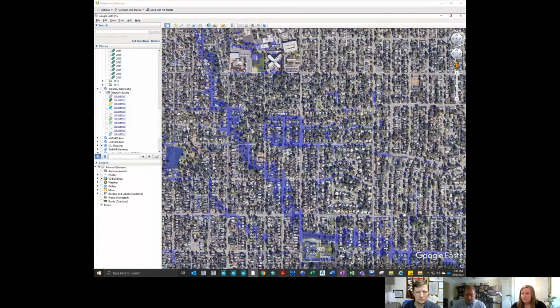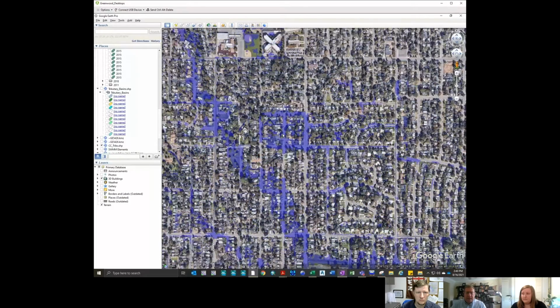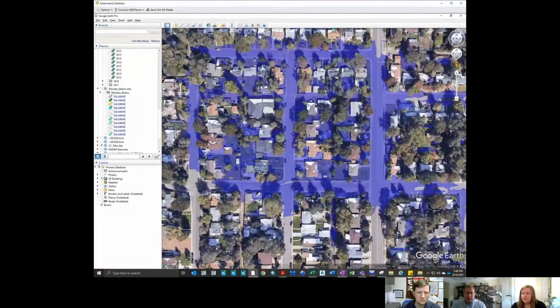Let's go identify some other low spots that we have here. Here's a location where our basin delineation did not cover or find this low spot, but our pluvial flooding did. As we zoom in, you'll notice that it's starting to show a low spot that has backed up water, that we're starting to see individual houses where the pluvial flooding is not spilling down the street, it's not being collected, and we need to identify this as an area of interest to do further study.